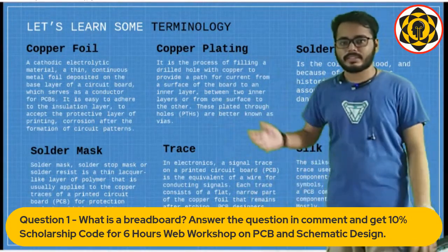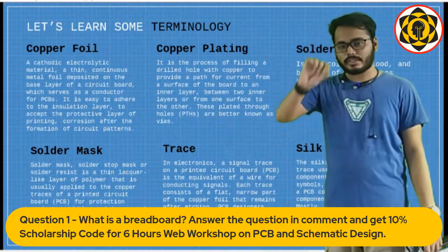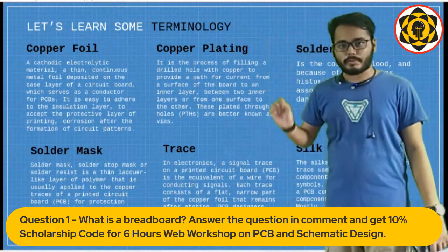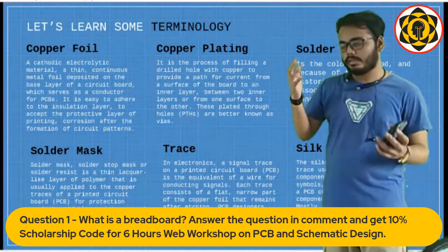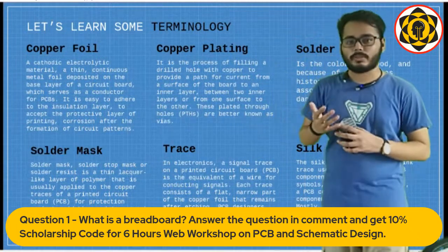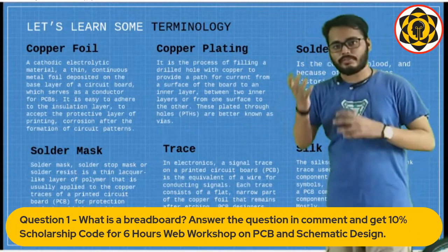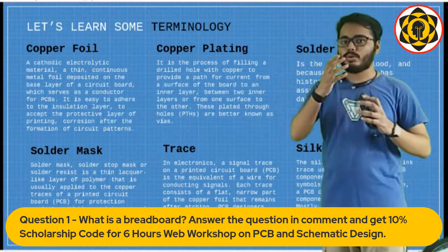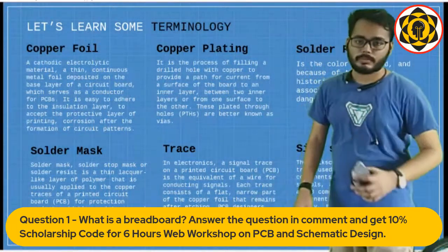The purpose of the silk screen is to have certain specific instructions on the top of a PCB. Those are literally minimalistic, like they only have the names of the component in a short form or stuff like that, so that you can understand from that reference where you have to place which component.